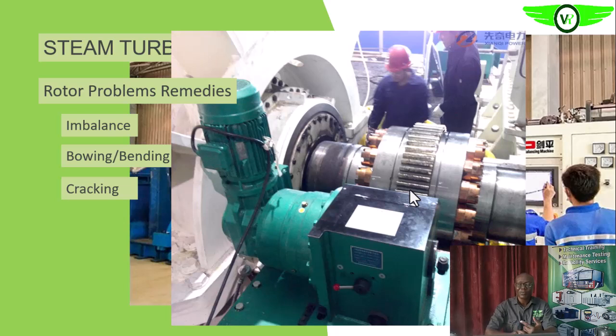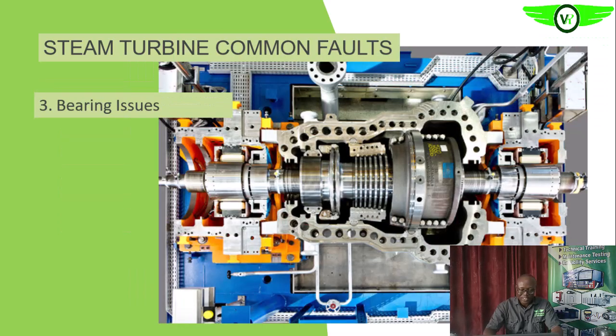Use the appropriate material for the design of the steam turbine parts, the rotor in this case. So erosion and corrosion is something we can prevent by maintaining the quality of steam that is entering the steam turbine. Also, they need to use the right material that will be able to resist corrosion and erosion that may be associated with the operation of that rotor in the steam turbine, as we said earlier.